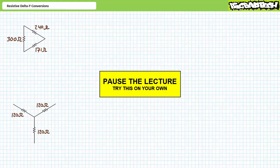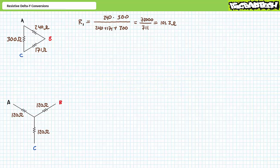This being said, identifying errors might be hard in a free-for-all, and as such, let's say the top left node is A, the middle right node is B, and the lower node is C. You'll note the second illustrated example features 3 identical elements. You should notice something interesting about the resultant conversion. If you're tracking, you should have obtained the following results. Our first illustrated example features a delta configuration of 3 resistance elements, and we're being asked to convert it into an equivalent Y configuration.